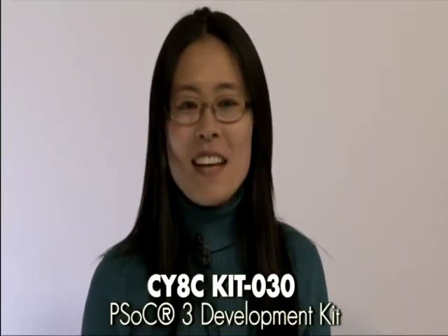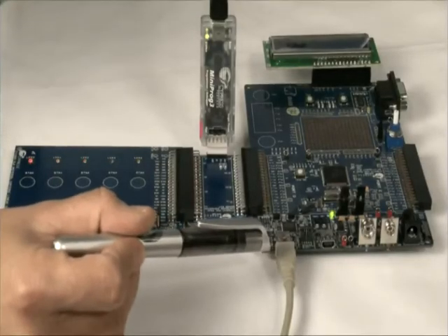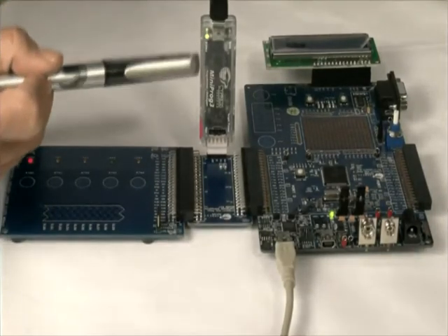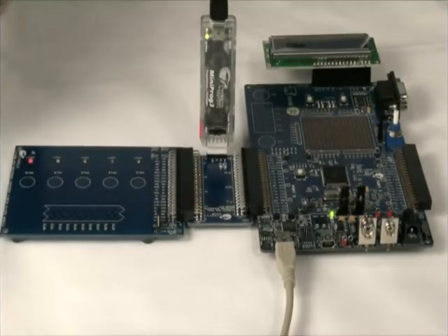The hardware I'm using here is the CY8CKIT-030 PSoC 3 development kit. This kit allows you to develop precision analog and low-power designs using PSoC 3. Now, the extension board here allows you to develop your own expansion board and plug it in from here and then build up your own ecosystem. The USB port here is used to program and power the board, and the MiniProg3 programmer here serves as an I2C bridge to read the CapSense data back to the PC.